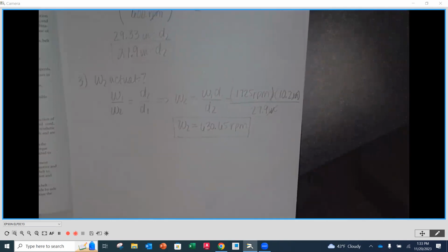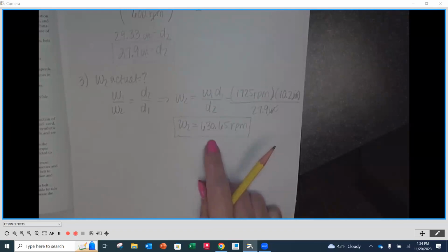What's the other issue? There's another one. The rotational speed. I don't think 630 is approximately 600. I would want to see us be in between, maybe plus or minus 5 RPMs. But to me, you as a designer make that decision. I would go back and reiterate this. Okay? For those two reasons. Number one, you don't want to be on the edge of standard sizes. And additionally, this is not to me approximately 600. This is plus 30. That's a lot. Okay?